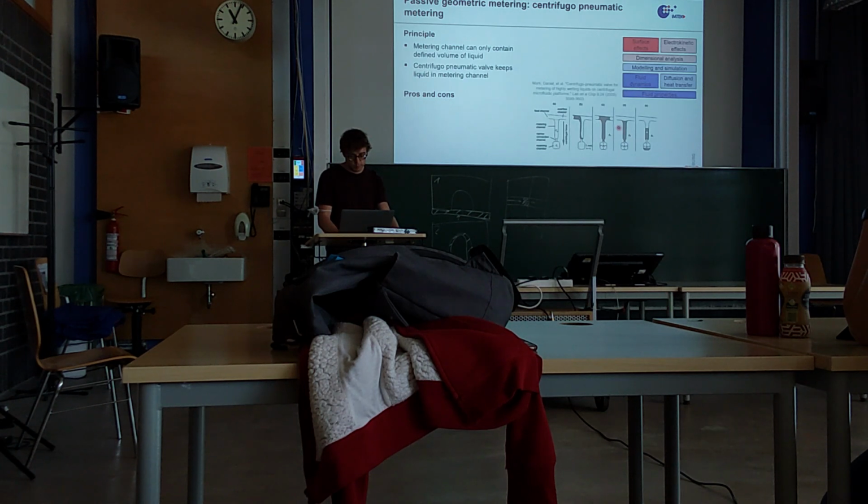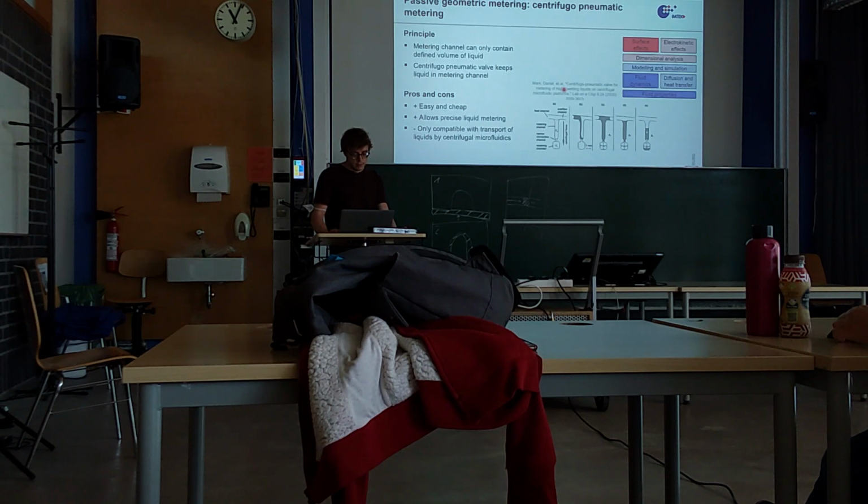This liquid is held in position because you have pressure that builds up because of the compressing of the gas, and you also have a capillary restriction at the bottom, and these two forces and pressures will be in balance with the centrifugal pressure at this position, and that's how you meter your liquid in this case. So what I said before is valid for this concept as well. It's a passive concept, so it's easy and cheap. Nevertheless, the precision is quite good in this system, but it only works with centrifugal fluids.